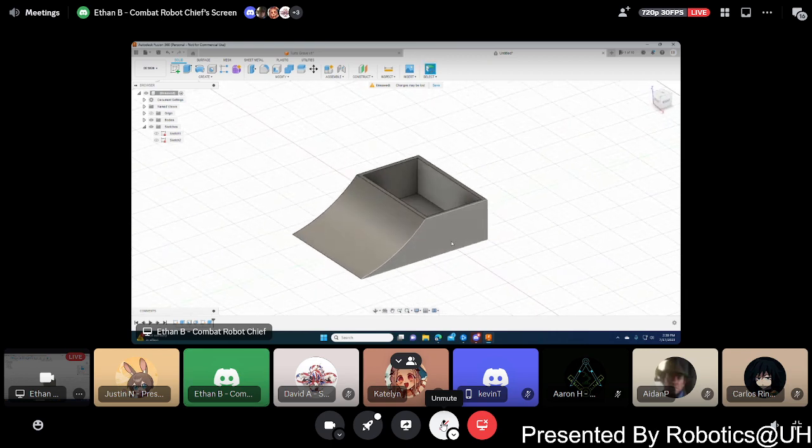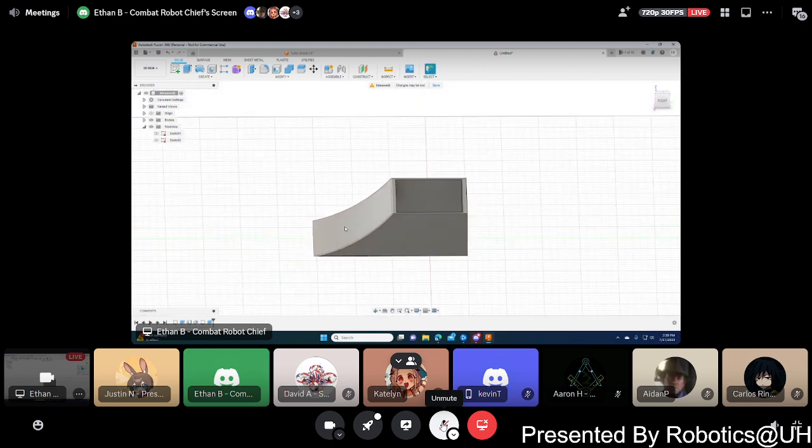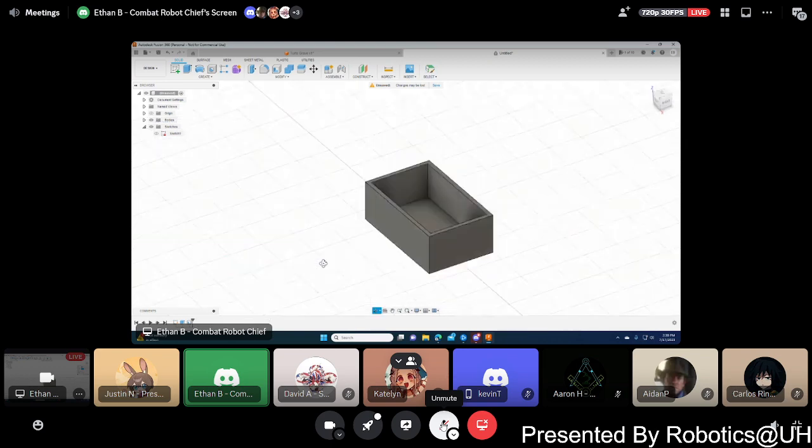Let me think. Oh, I know another thing to do. Let me think on what I could do to implement that. Instead of doing that, I can go back on the times table to before the draft. I can right click any point afterwards and just click delete features after history marker. I'm going to show a different way to make that draft.